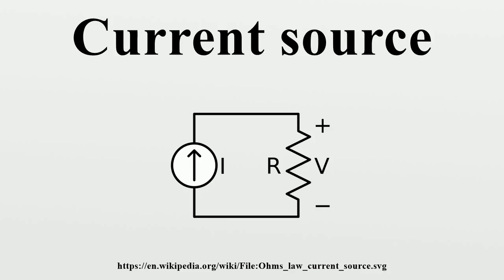Simple transistor current sources. Constant current diode. The simplest constant current source or sink is formed from one component, a JFET with its gate attached to its source. Once the drain-source voltage reaches a certain minimum value, the JFET enters saturation where current is approximately constant.